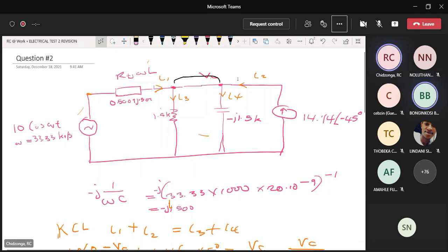You can see my arrow circulating around there. How many wires would come to that point? One, two, three, four. Yes, there will be four wires. One for this, two for this one, three for that one, four for that one. So where is the short circuit?